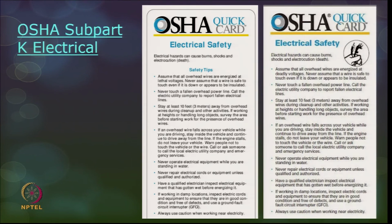Never operate electrical equipment while you are standing in water. Never repair electric cords or equipment unless you are qualified and authorized. Have a qualified electrician inspect electrical equipment that has got wet before energizing it. If working in damp conditions, inspect electric cords and equipment to ensure they are in good condition and free of defects, and always use a GFCI. Always use caution when you are working near electricity.